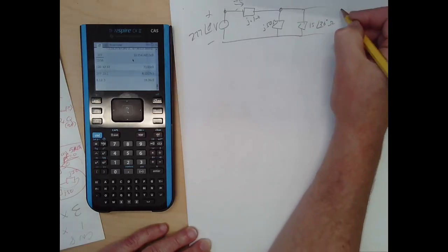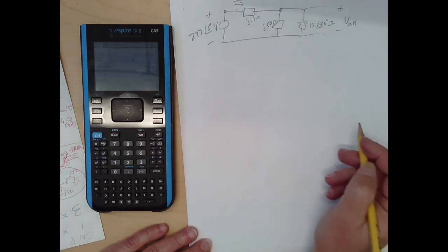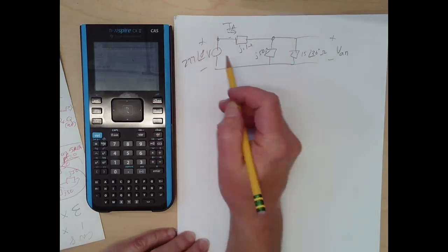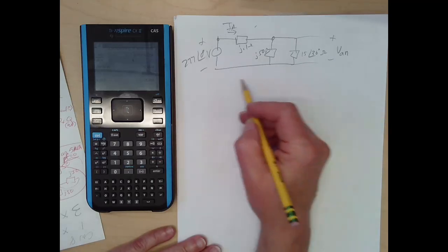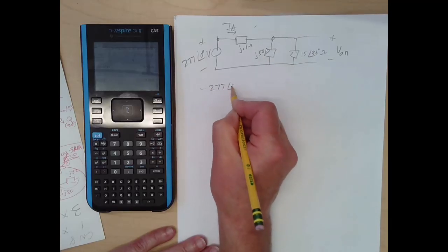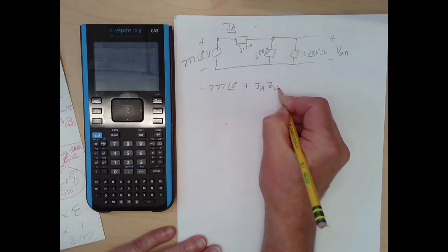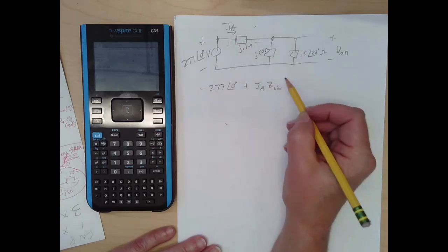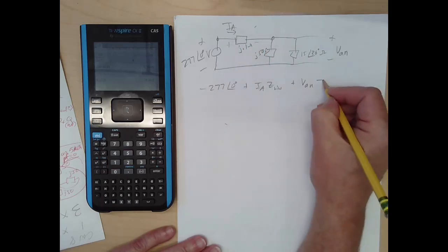All right, let's say we want to know the voltage here, V little a N, line voltage at the load, right? We would expect that the source is holding up the voltage, right? The source is providing the power, holding up the voltage, and so the voltage is going to drop across the line and be lower at the load, right? So let's just do KVL around this. Pick one of these loops. And so we would have negative 277 angle 0, so negative V source plus IA times Z line, or J.1, right? You're doing the KVL, Ohm's law, IZ, and then plus, and we're looking for VAN, so let's just write it as VAN equals 0.